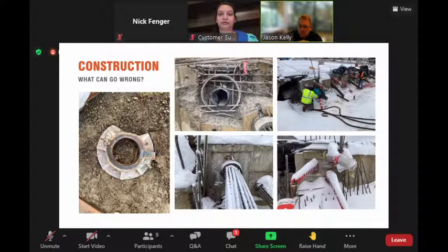That's what happened on one of the ducts they were doing out there. They were tensioning, they were about done, and then they heard this loud crash. They're like, what's that? Well, at the far end of the bridge where it was anchored, there were some voids behind this ram back here in the concrete, and the plate that they were pushing against crushed and snapped and broke. That's what this top corner is. They had to go in there and dig all this concrete out, get all the defect and the void out, reform it, and pour it. So you never know what's going to happen.